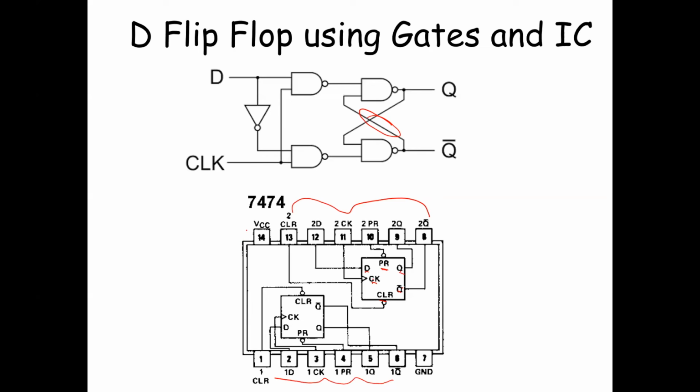Okay, and then this is not a passive circuit, which is clear from here. This needs to be connected to VCC. This needs to be connected to the ground. You need to see the spec sheet on what VCC you need to connect it to, so what voltage will do. Unless you have that, you cannot get this to work. Now, your computer probably has thousands of these flip-flops, and they're very tiny.